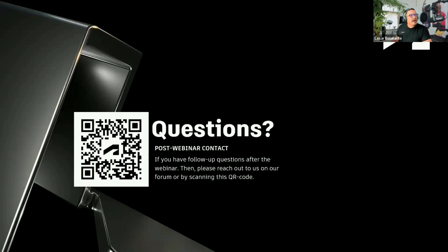Here's a question from Maya. How did you get such a detailed Rhino model in Forma? Is there a limit on how big your Rhino file can be when integrated with Forma? There's no limitation on how much level of detail you want to get into. Forma has the ability to import a Rhino file in whatever state it is, but for analytical purposes, there's a limitation of 150,000 polygons. I need to get back to you and check what happens when we exceed that threshold, but the recommended geometrical limit is that.